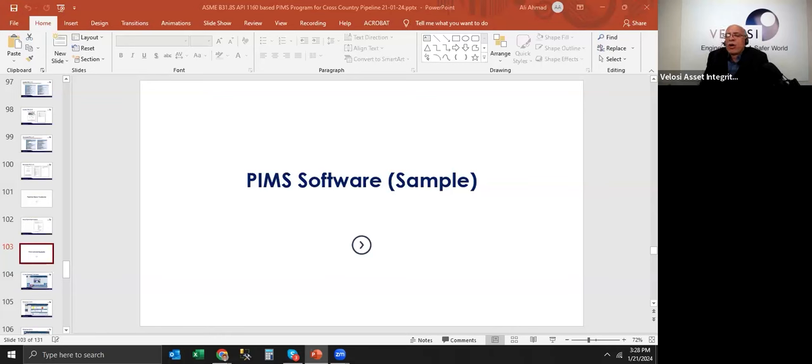Similarly, CP is cathodic protection, where we provide electric current to compensate the loss of electrons of the pipeline due to corrosion. So CP is basically compensation by artificial electric supply. That is the system, and CP itself is a big subject, covered in a separate webinar. Next, please.